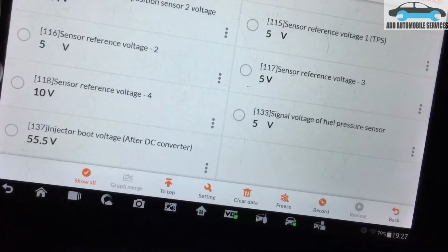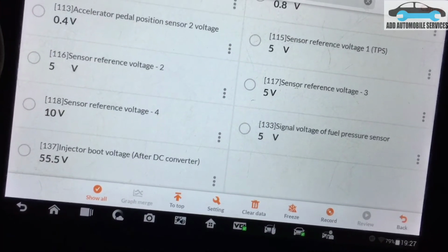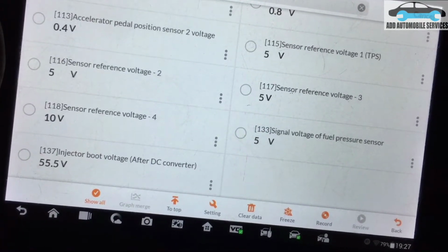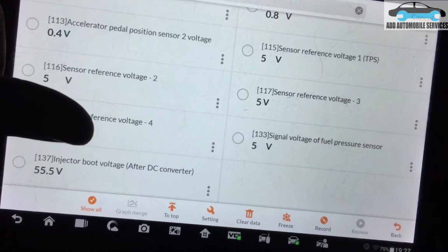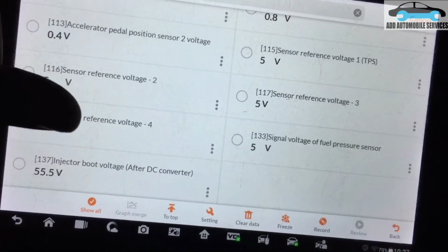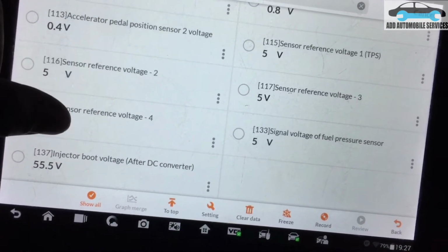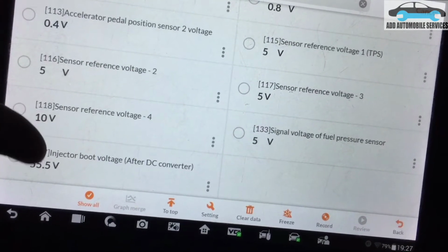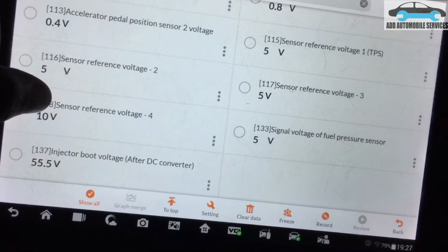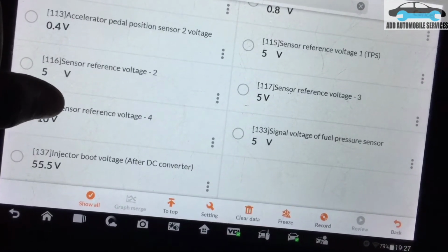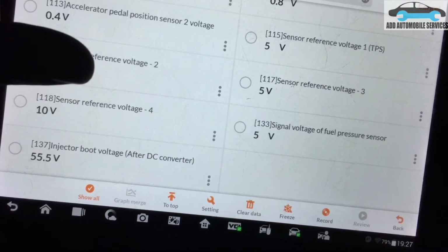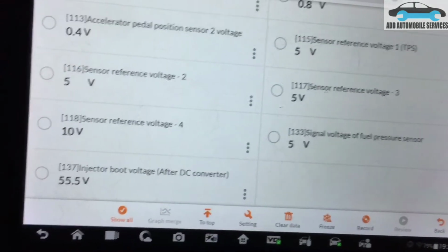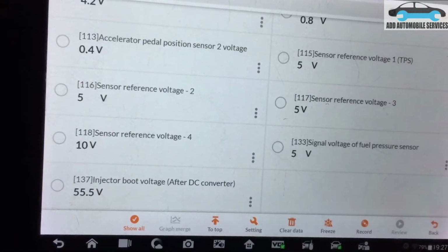So what I'll do now is attack the fuel pump pressure sensor first and find out where it's getting its 5 volts from, because I don't know why it should be 5 volts. If it's a signal voltage it should be below 5 volts. If it is above 5 volts, then there is an issue, and the issue will be from the sensor voltage reference, the one supplying voltage to it. So I will check it, find out the actual problem and continue the diagnosis.